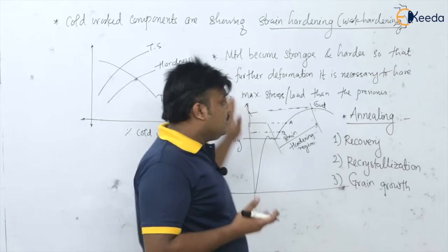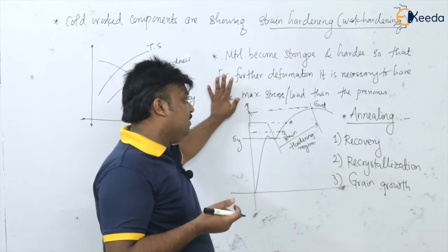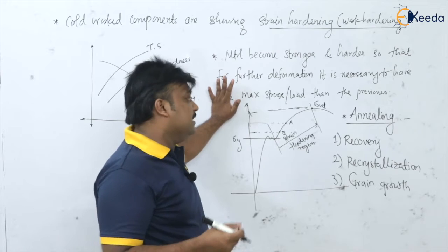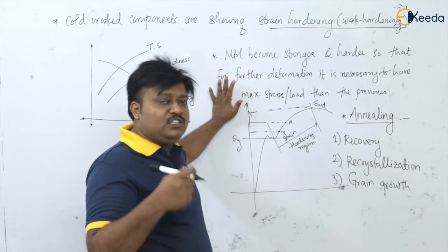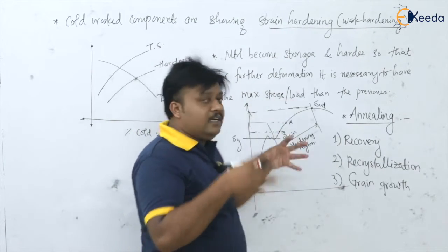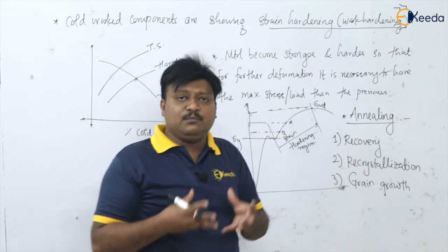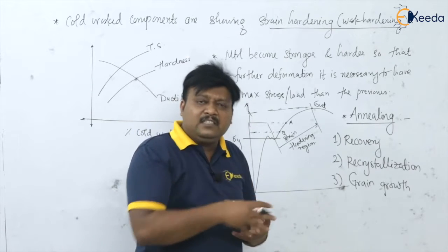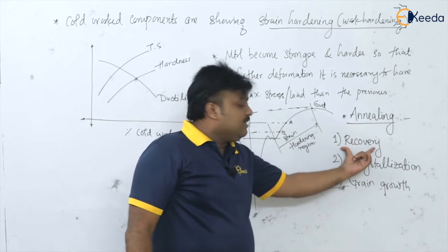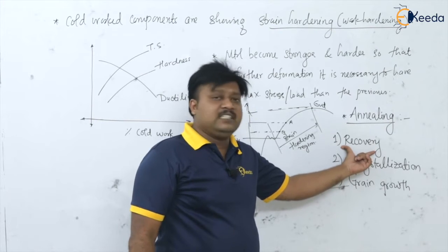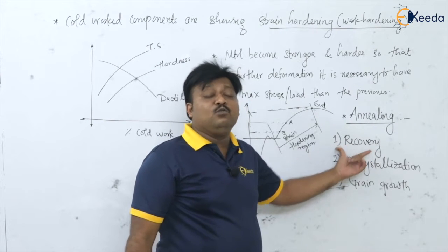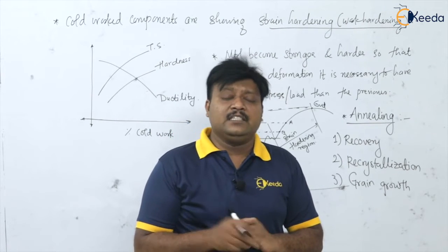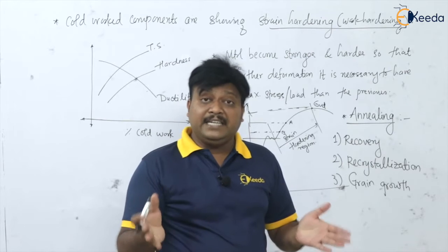Recovery. The temperature is somewhat lower. Here whatever residual strain or residual stresses are in the material, in the form of energy pockets, the bundles of energy because of the working, straining of these grains, whatever the IRS, internal residual stresses are there, we are just trying to relieve those to give certain mechanical properties for the material.